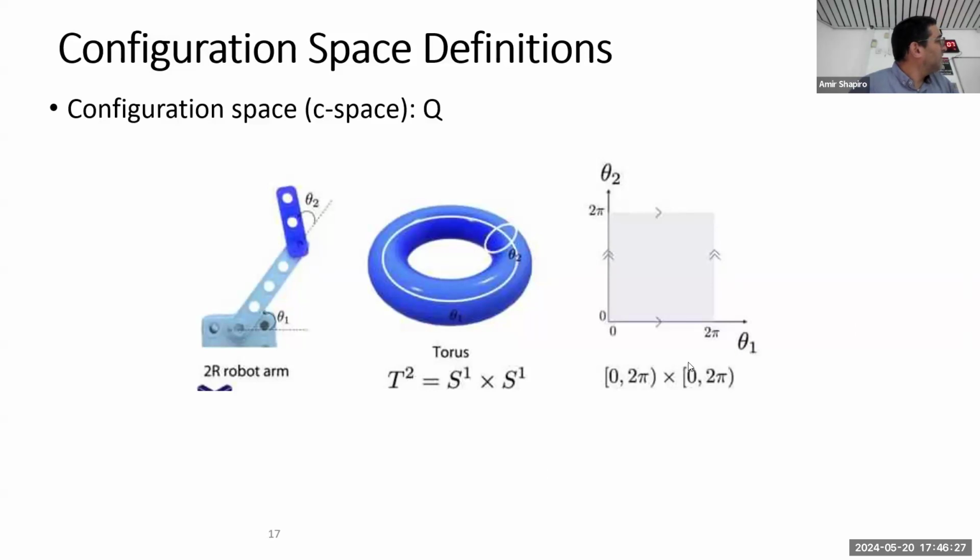Yeah, here or 0. 0 and 2 pi both, and pi also. 0, 2 pi and pi, and also in the center. But it doesn't matter because the robot can move through a singular point. It's not a problem. It's a computational problem, but not a real one. It's a real point that the robot can move through.